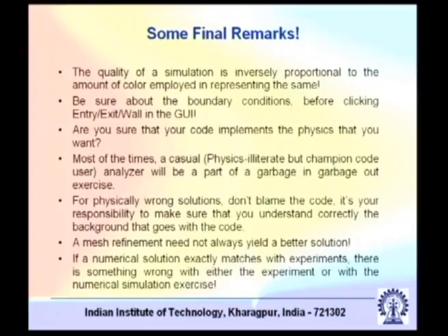Now the other thing is that when you have a solution, how do you validate it? CFD problems have benchmarks. There are some standard benchmark problems in the literature, and you can validate your solution with them. Sometimes you validate your numerical solutions with experimental results, but if a numerical solution exactly matches with experiments, there is something wrong with either the experiment or the numerical solution.